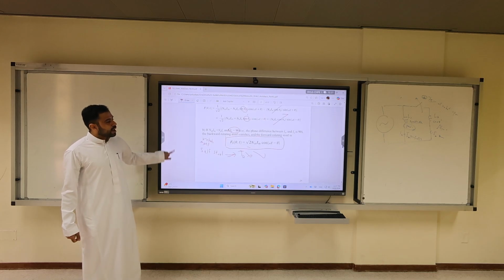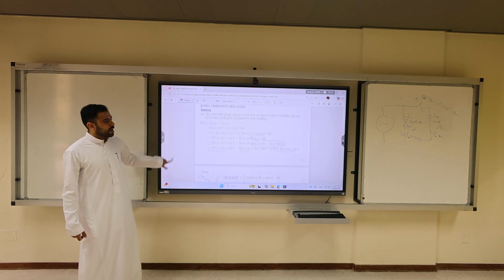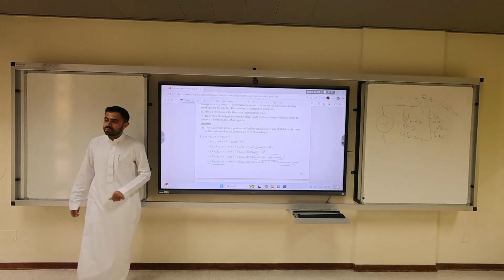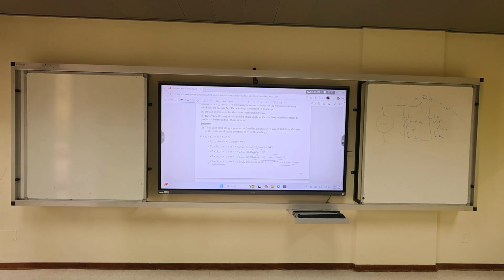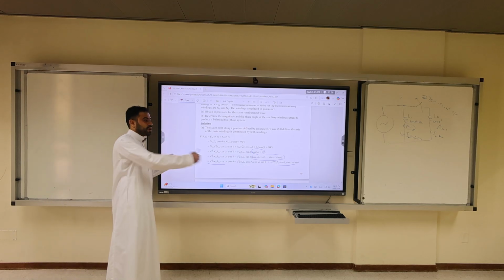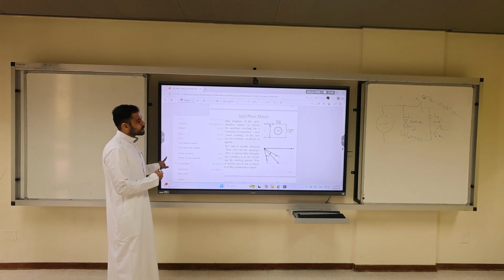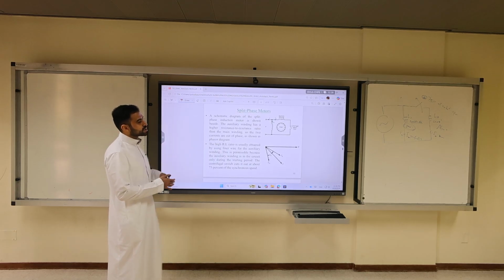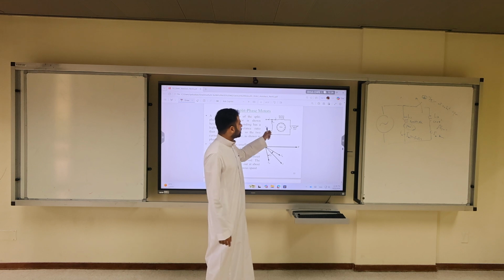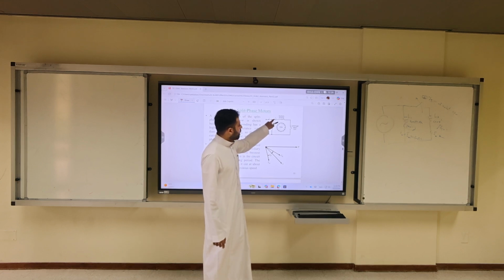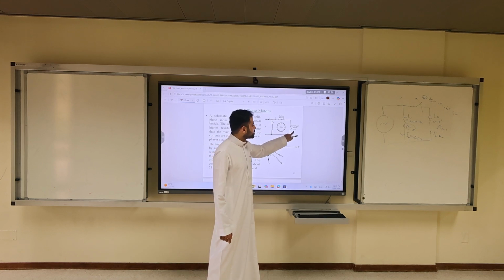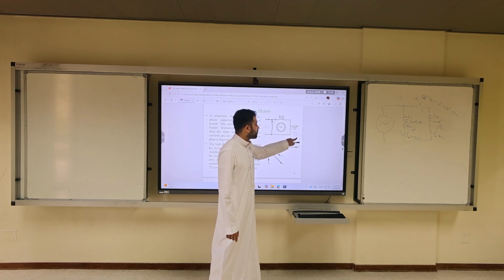Okay. So now, after I have the auxiliary, and now they are rotating, I face a problem: do I really want a two-phase system all the time? Remember, it's a single-phase machine. There are many methods to keep the operation running, between start and run. The first is the simple scheme where, similar to what I explained, you have the main, you have the auxiliary, and you add a switch that closes at 75% of the rated speed. Okay?